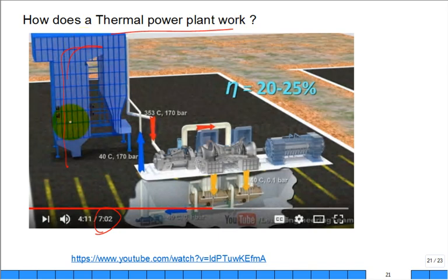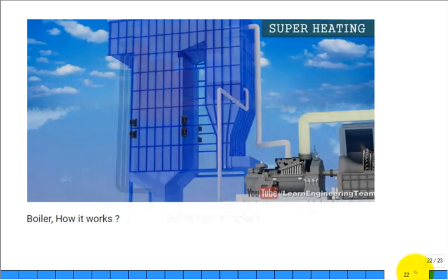Over here would be the boiler. And that's maybe the coal pulverization and what it looks like in the firebox and the tubes and this heat exchanger here and there. Then steam comes over at this pressure and temperature, expands through the high pressure turbine, maybe goes back for reheat, maybe goes to the intermediate and low pressure turbines. There's our electric generator, overall thermal efficiency. This is what we've been talking about, right? So instead of just pieces of paper, you might find these very helpful to understand what's going on, even just talking about superheating and the boiler and how it works.